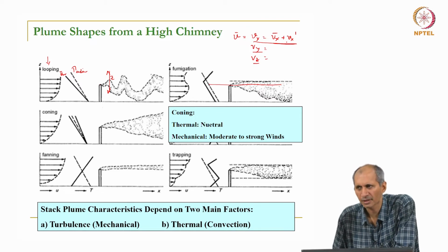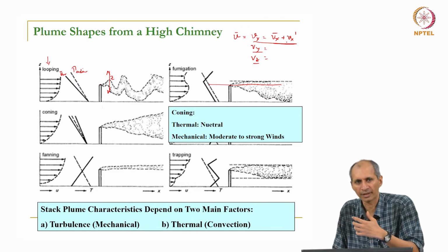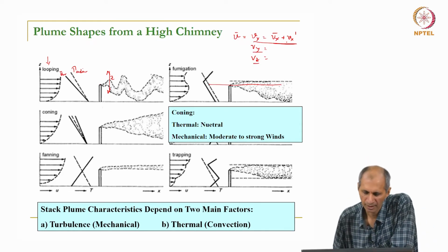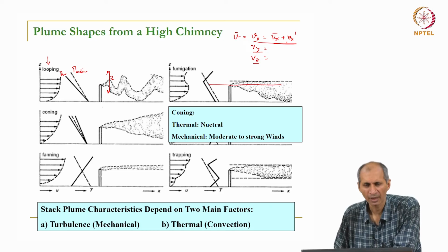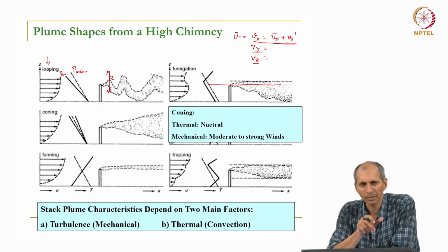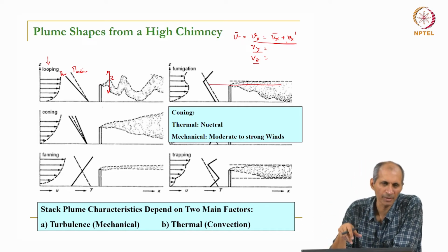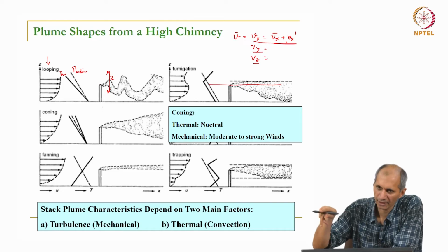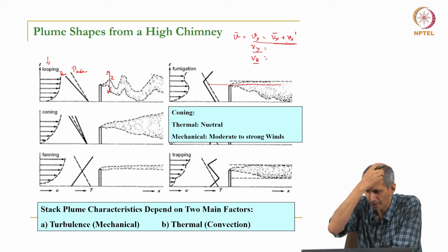In chemical engineering literature, this is called dispersion. It's all back mixing. Any presence of any eddies results in back mixing, and that is termed dispersion. This is not to be confused with another term called diffusion. Diffusion is a different phenomenon. Dispersion is mainly because of these eddies, the circulation patterns that are formed.